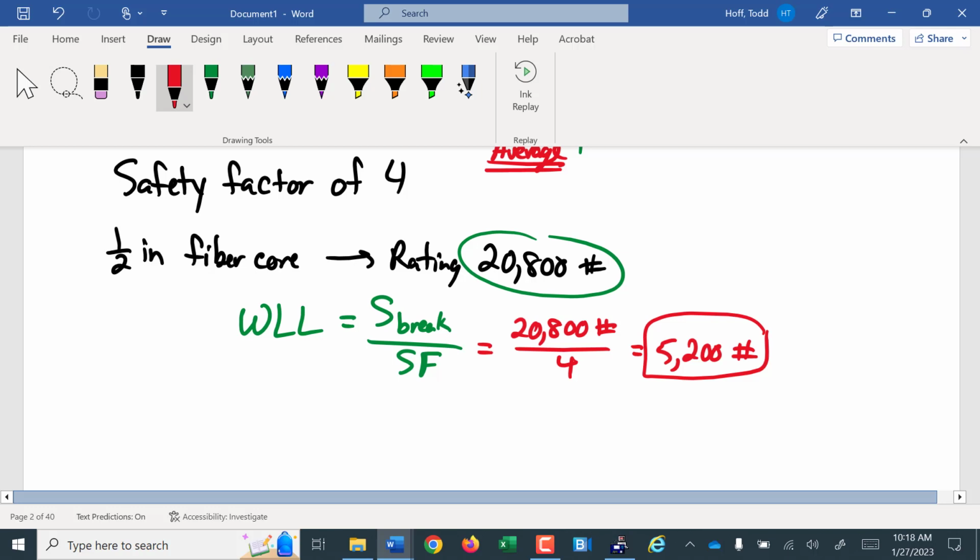Yeah. I mean, it's just like when you're doing roofing on a house. Most people stack the shingles at the peak. Well, that's at the midspan of the roof truss. That's the absolute worst spot to put them. That gives you the absolute most stress on the roof. The safety margins in the roof account for it, and you don't have issues usually.